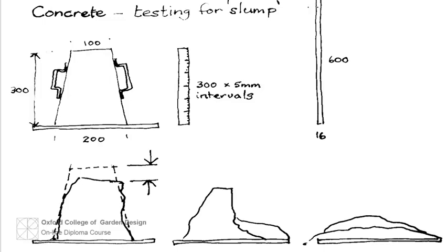I will not spend time now discussing formwork for concrete, because this is where a specialist contractor's expertise must be available to help create the effect that you want if the finished concrete is to be exposed to view. Reinforcement is normally mild steel, which is liable to rust. Rust has a greater volume than the original steel, so this expansion eventually causes the concrete to split open or spall.